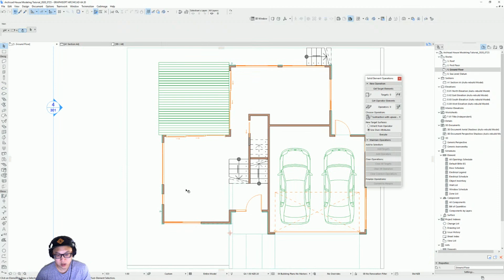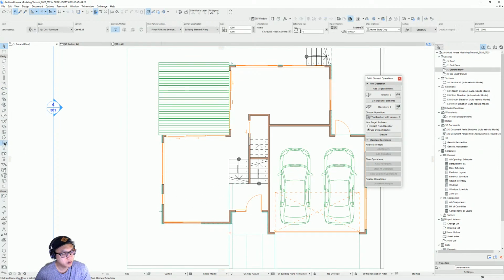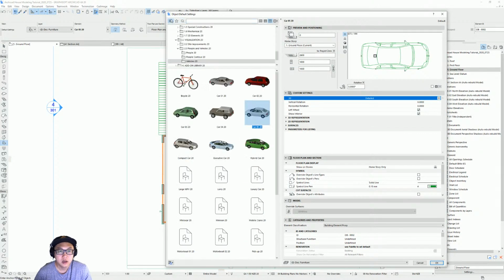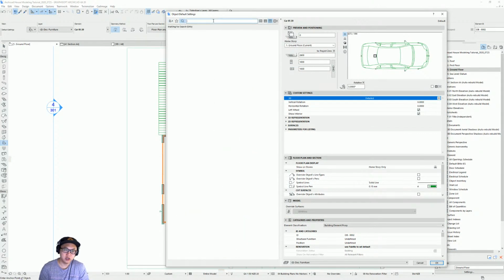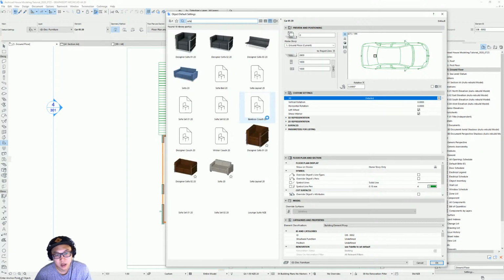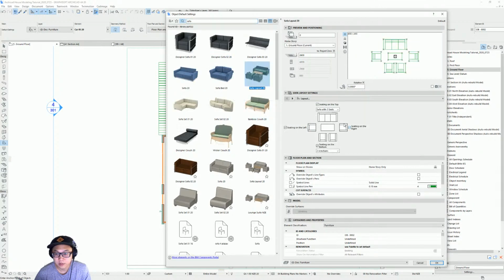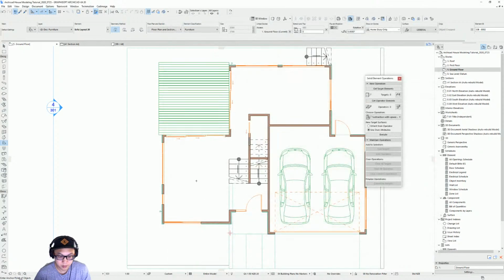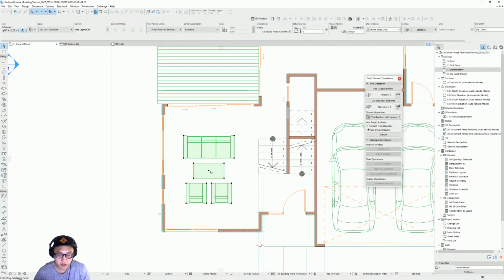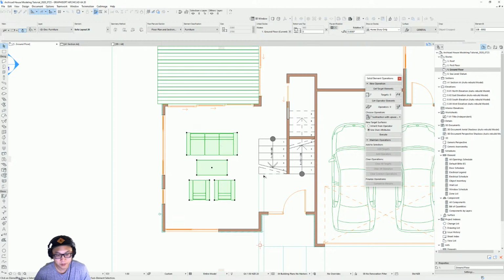And a living room area there. Here, and I'm going to type it. Usually I just type in sofa. And I like to take this one. I'm going to choose move those two, and press OK. Bring it here. So now I get my sofa. I usually use the walls here as a reference to center it in the room. See the little point there.